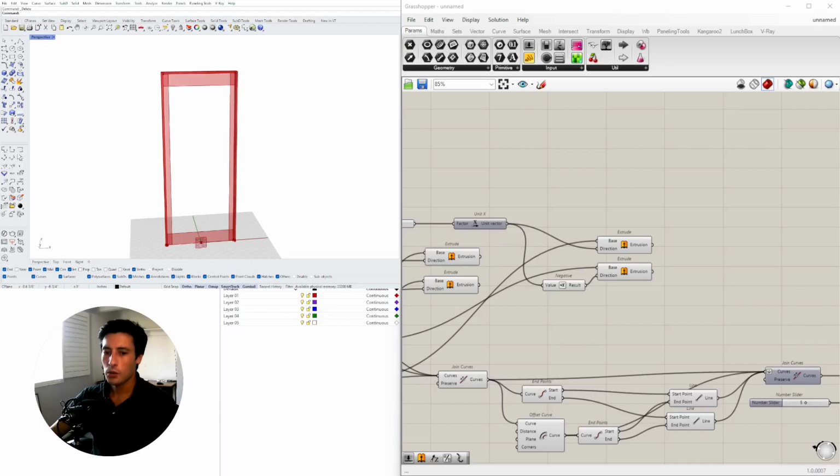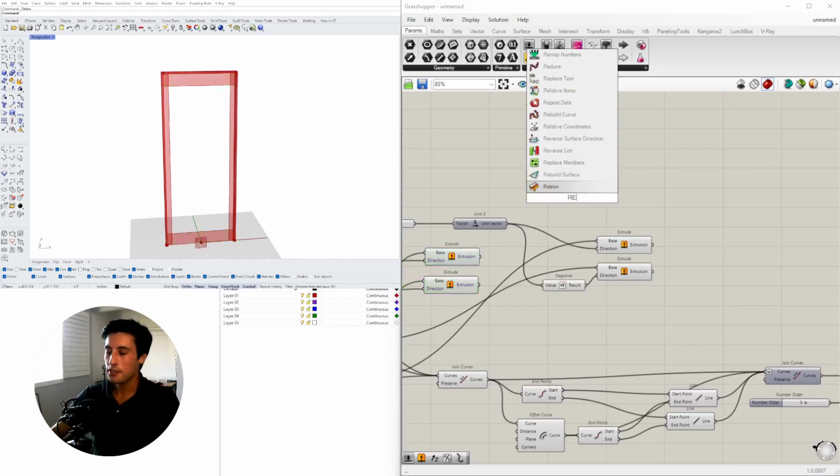Let me take a look real quick here on Google. I did a quick search on Google, and typically the side rails do go all the way past and trim the top and bottom. So knowing that, top and bottom are going to be subtracting this side. So we'll go here to region difference.